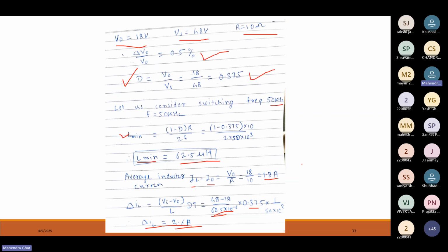With higher switching frequency, all the inductors and capacitors get reduced, and you get a smaller size. But for that, people are now moving to GaN devices. GaN is a device which can operate at a very high frequency, almost 500 kilohertz, 1 megahertz. So in that range the converters are now operated to make the chargers.